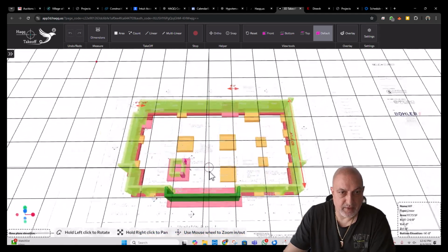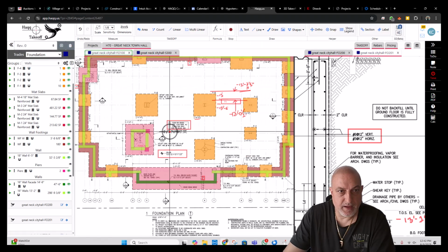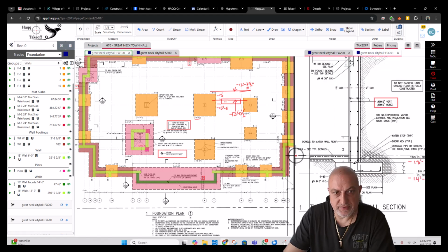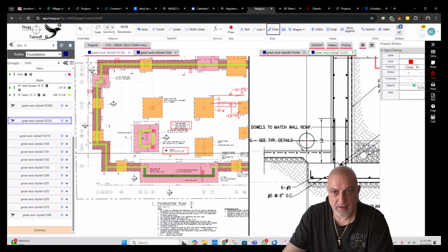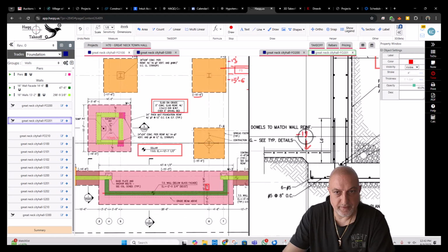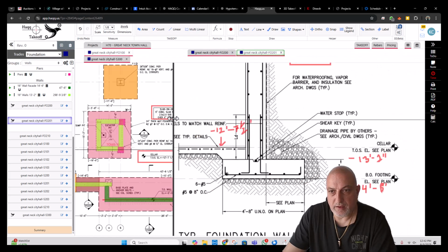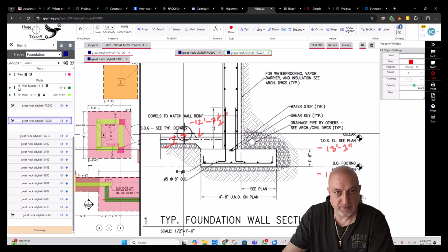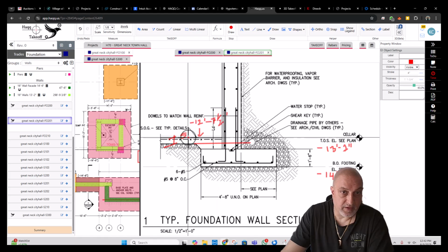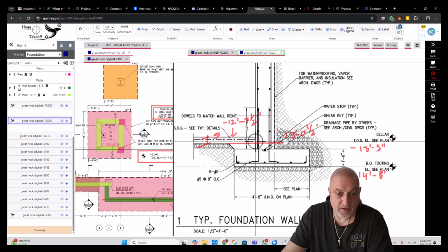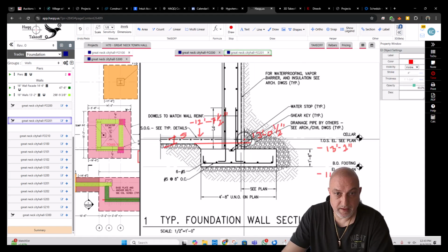Now we're going to add the slab on grade and we'll be done with this foundation. As you can see, the slab has the hunch. Let's figure what we figured for the hunch here. This was minus 12 foot 7.5, and a 5-inch slab thickness. So 7 plus 5 is 12, so 13 feet 0.5 inch. This is an inch and a half. Hunch. Okay.